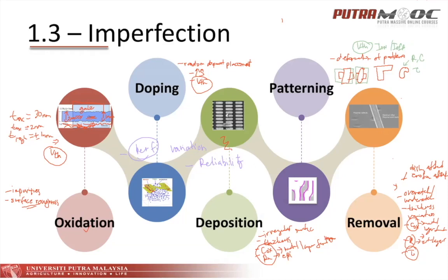Doctor, is this something related to a time delay? I mean, I'm just guessing. Yes, it's a good guess. It depends on the time, all right? When you are doing final tests, for example, and you observe threshold voltage variation, that is what we classify as performance variation. That is before we ship the chip to the customer. So that is performance variation, and reliability occurs after the product has reached the customer. After a certain time of usage, you start to see the issue coming in, right?